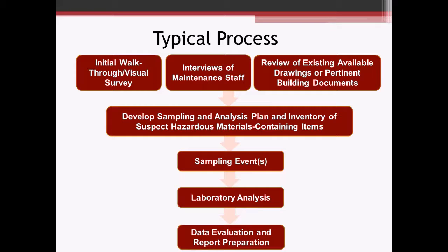You know, a big thing is things that might be hidden from view within a wall cavity, below a concrete slab that aren't easy to get to. Sometimes that building staff will be able to tip you off on what that might be, or even those building documents might say there's a vapor barrier under this slab, and some of the older ones even call it out for asbestos barrier membrane or something. So you get lucky with that, and hey, chances are you still have asbestos underneath that slab.